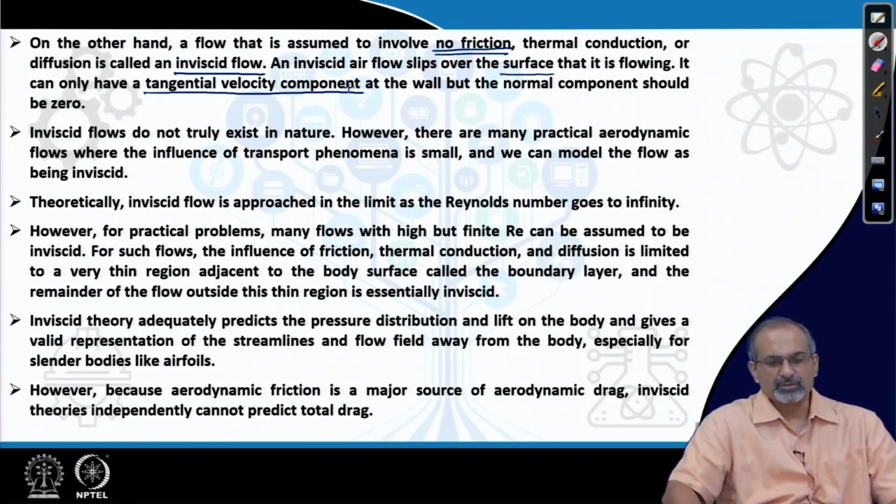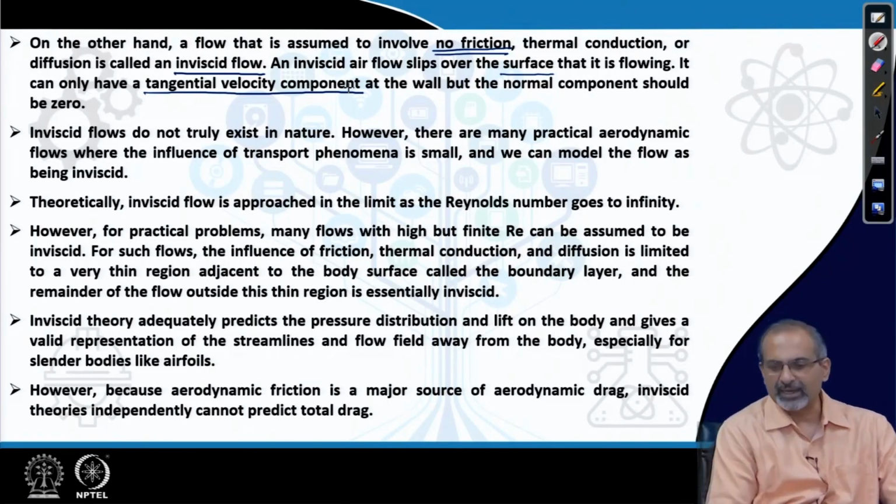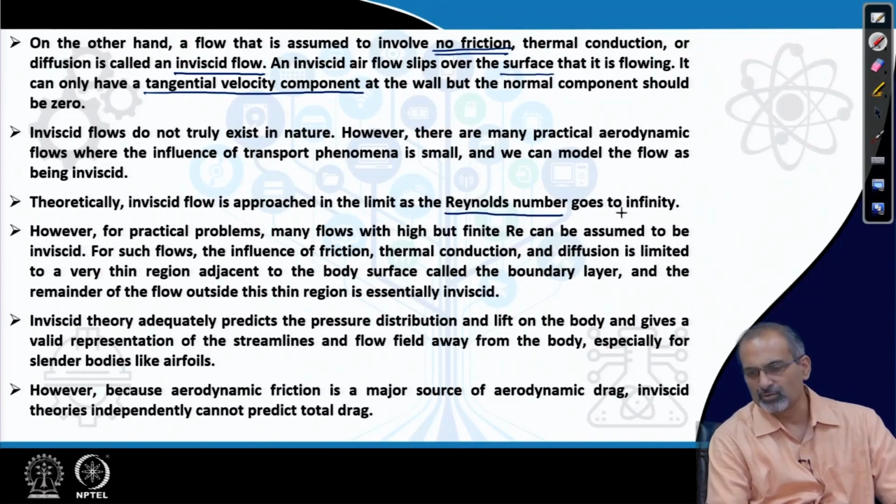Now, inviscid flows do not truly exist in nature, they are basically hypothetical. However, there are many practical aerodynamic flows where their influence is very small, and we can model the flow as though it is close to inviscid. Theoretically, inviscid flow is approached in the limit as Reynolds number goes to infinity. We will discuss more about Reynolds number. It is one of the very important non-dimensional numbers, which is of enormous importance in aerodynamics.